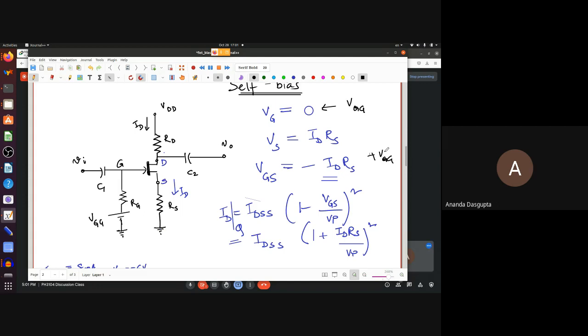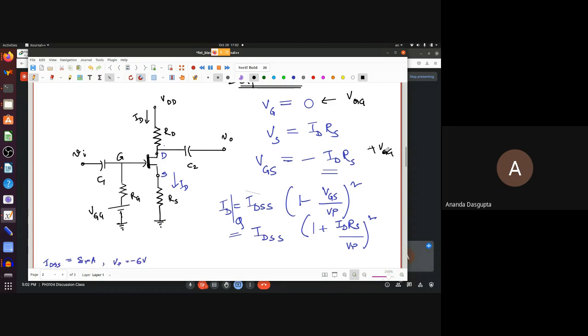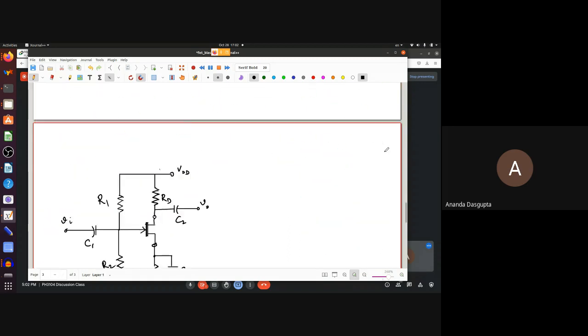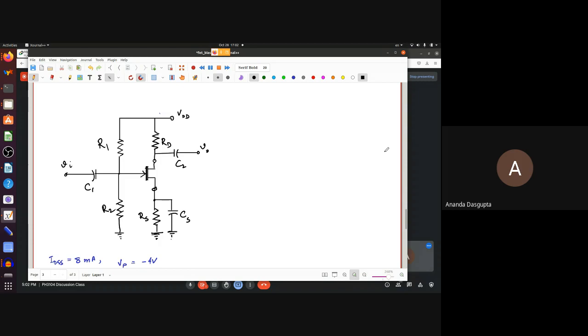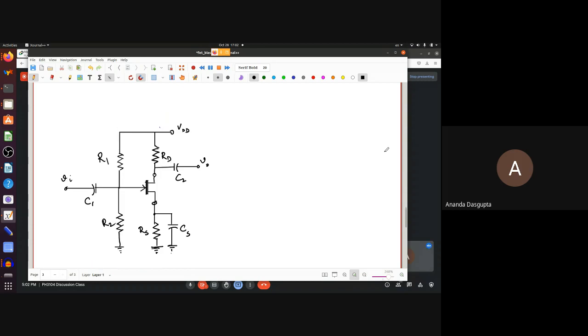Come on. You told me that at the very beginning. What's bad about using two batteries? Cost. Yeah, but how do you make the circuit believe that there are two batteries even if there are not? A potential divider. Exactly. So the final circuit that we have is this. That's a JFET circuit. Very nice circuit.